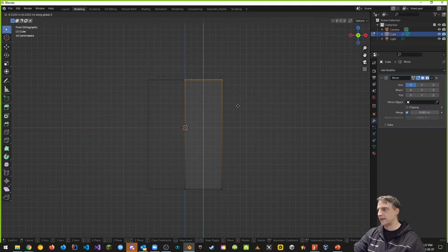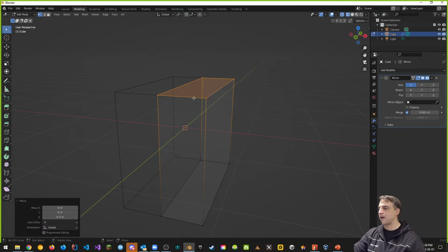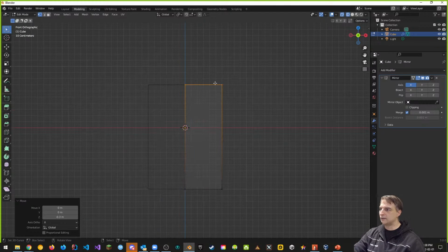And then you can move this down to where you want it, which for me is going to be something like this. On the left, when I do that, it says the Z transformation is minus 0.3 something. Let's change this to minus 0.3. Just typing it in there. And now we have the box that's down minus 0.3. On the right, we've moved in 6 units instead of the whole 2 meters. Remember, this whole thing is 2 meters from here to here, but we only play with 1/2 of it, which is only 1 meter.